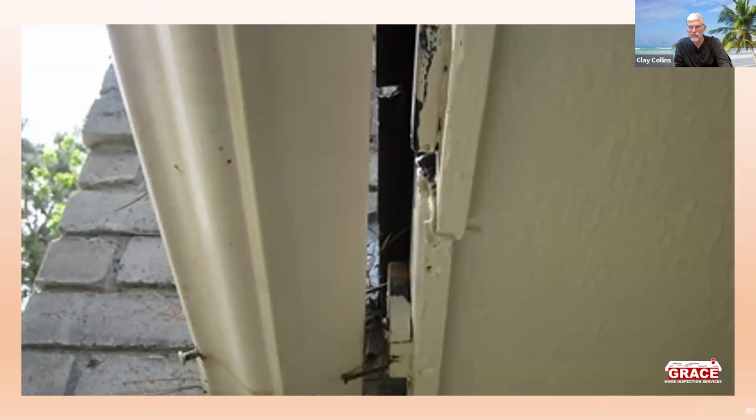Here's where you have the deterioration behind the gutter. I don't know anything about the drip edge. From this picture and the shiny spot near the top of the page, it looks like this does not have a metal drip edge, roof edge flashing, and it's just the wooden drip edge that's deteriorated. And you can see the gutter, the nail pulling out at the lower left, but you also see that the roof, no, that's a brick, never mind. But you see the nails are pulling out.